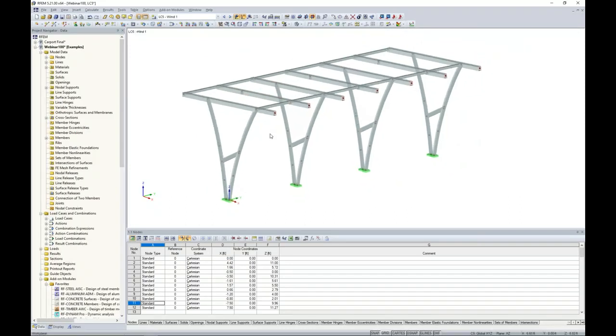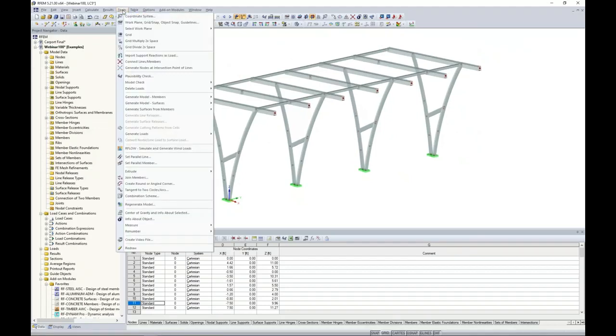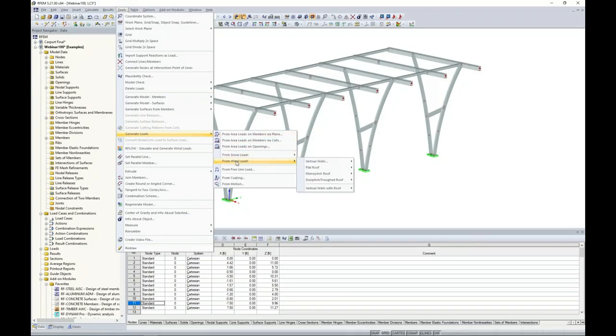Now for wind loads, we do have an automatic wind and snow load generator. Now the snow load generator would be efficient for this canopy type structure. The wind loads unfortunately cannot be used because we only have partially enclosed and enclosed structure for our wind load generator. Typically for canopies, you would be considered as open structures. So we will need to manually apply our loads for today.